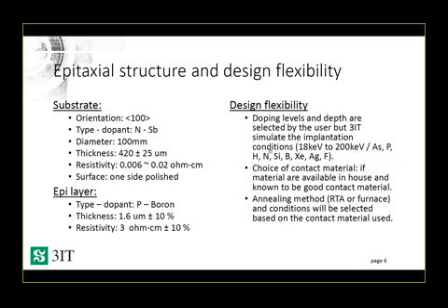So either one can be used. It really depends on the material that we're using and the best conditions to make a good contact for this material. For the ion implantation, though, furnace annealing is absolutely required because of the high temperatures required that the RTA just cannot achieve.